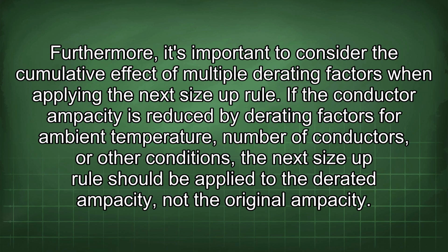Furthermore, it's important to consider the cumulative effect of multiple derating factors when applying the next size up rule. If the conductor ampacity is reduced by derating factors for ambient temperature, number of conductors, or other conditions, the next size up rule should be applied to the derated ampacity, not the original ampacity.